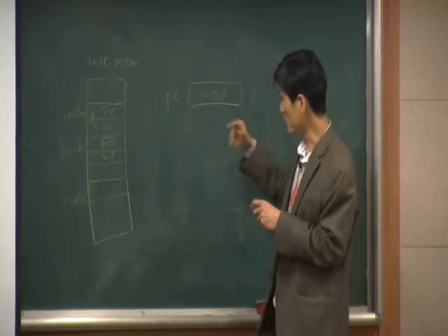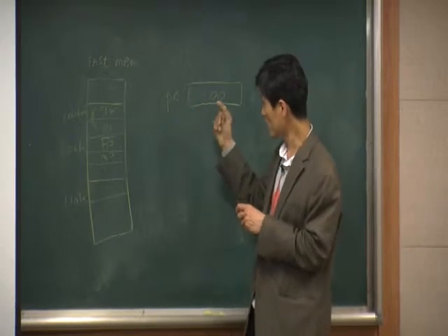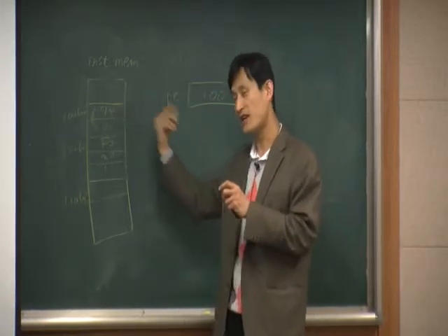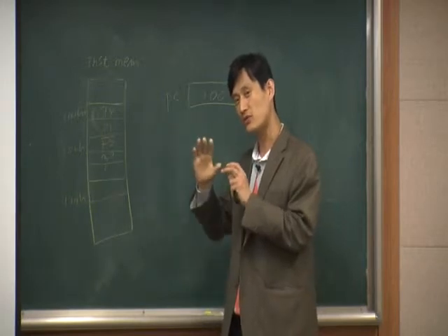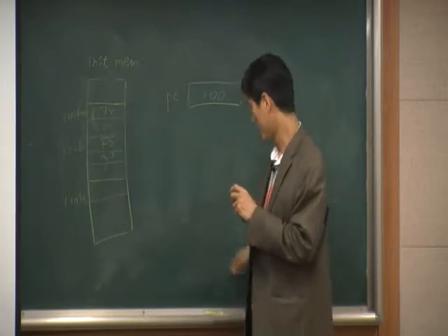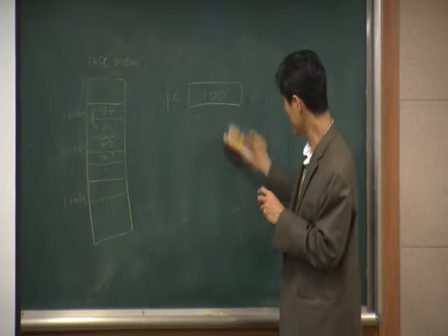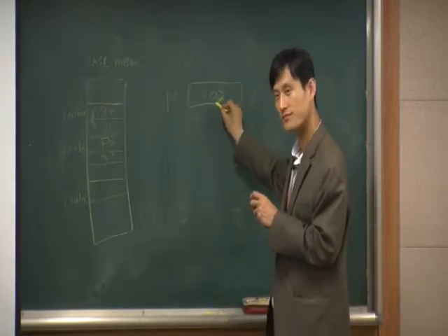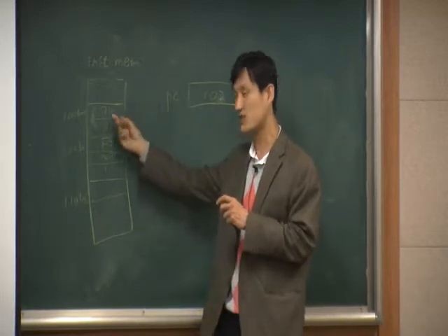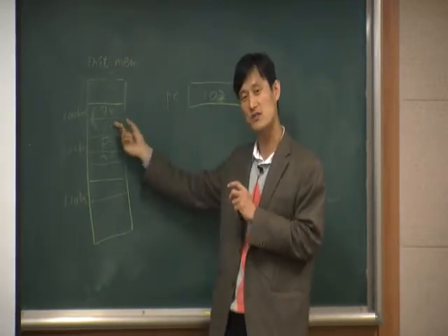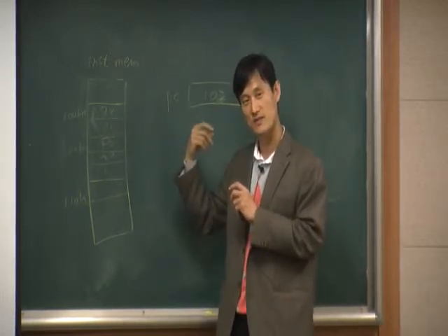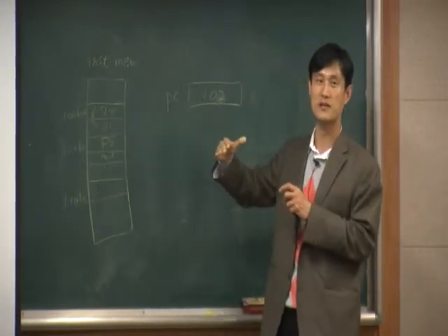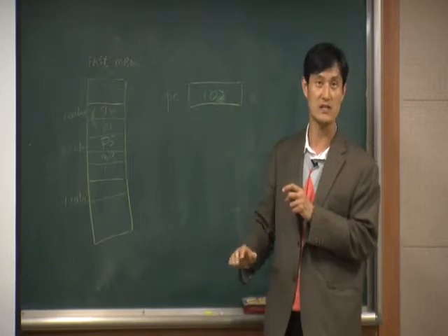When the microprocessor goes there and fetches, as soon as you fetch it, the PC is automatically incremented to the next instruction, because you already fetched the first instruction. Therefore, the value in the program counter will now be moved to the next instruction.